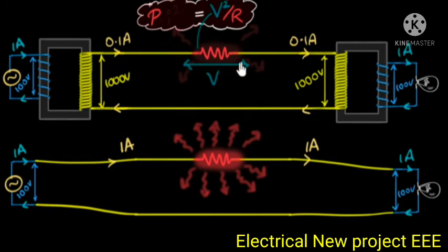And so, yeah, because there is some voltage drop happening, not all the 1000 volts will appear over here. Some of the voltage drop will appear over here. But that amount is much smaller than what you would get here. A lot of that 100 volt would appear over here. Does that make sense? So even voltage wise, if you look at it, power dissipated has reduced. Stepping up voltage helps in efficient power transfer.